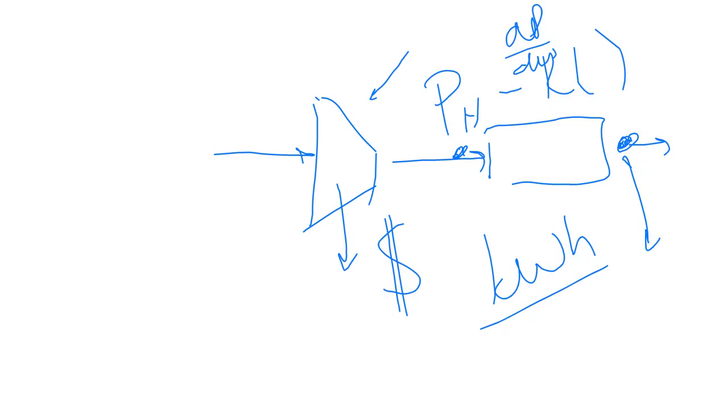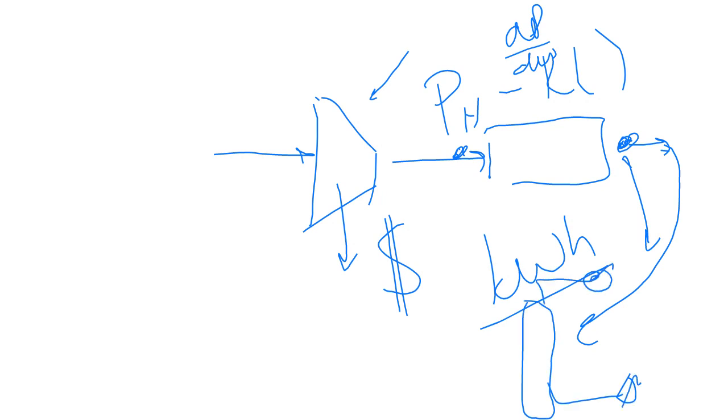Add an inert to increase U. If you add an inert, so what happens in your compressor, definitely you can. But adding an inert means that afterwards I am going to have to separate. And once again, that is a seriously expensive unit operation, which comes with its own set of control systems, that you must implement to keep the reaction rate controlled. Yes, that is what it means, yes.